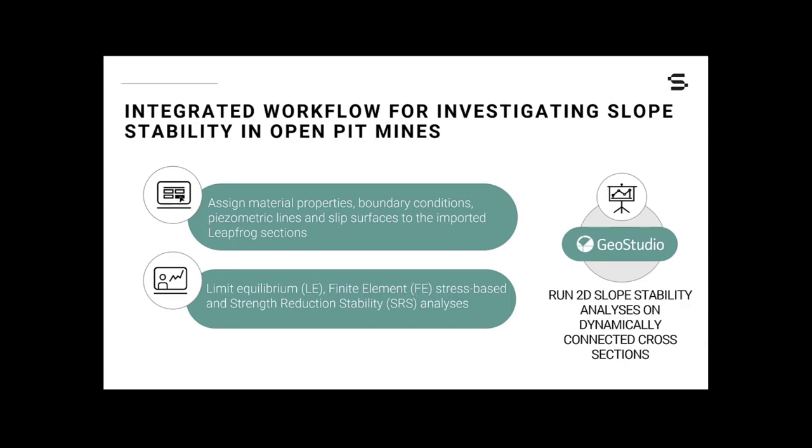Central also integrates directly with GeoStudio, so projects and sections that have been published to Central can be seamlessly downloaded directly to GeoStudio projects, negating the need to recreate geometries and reassign regions. Once imported to GeoStudio, material properties, boundary conditions, piezometric lines and slip surfaces can be added to the imported Leapfrog sections. From there, limit equilibrium, finite element, stress-based, and strength reduction analyses can be undertaken.